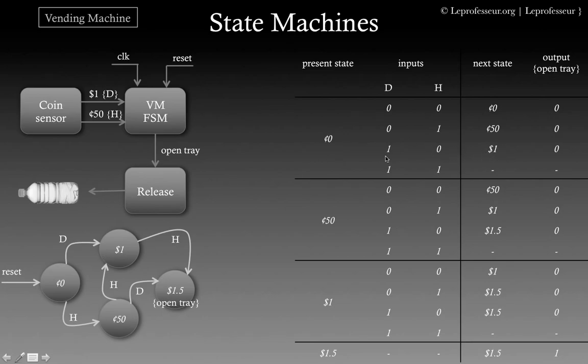So this table is very similar to the state table we discussed just a few minutes ago. We are basically translating this pictorial representation into a table, for better understanding, so that we can assign some state decoding logic and logic to get the output, and we can create a logic circuit.